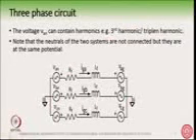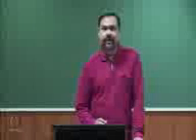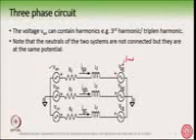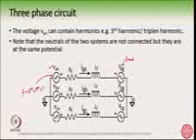Now remember that the voltage VAN, this voltage here, may contain other harmonics. So this may not be a simple fundamental. The grid voltage is fundamental, this is fundamental. But the voltage VAN here can have fundamental plus third harmonic plus 9th harmonic plus 15th harmonic, something like that.